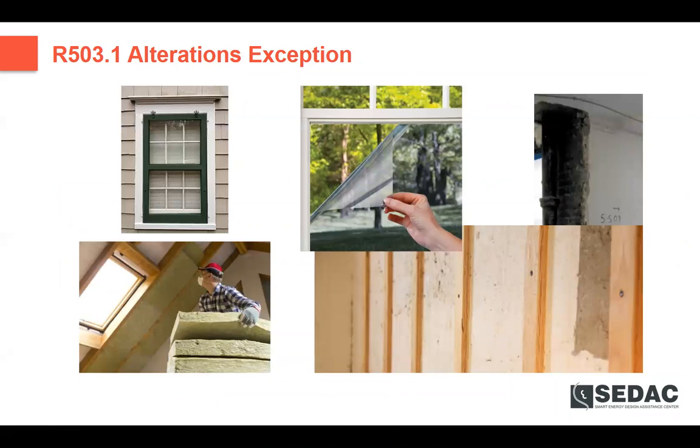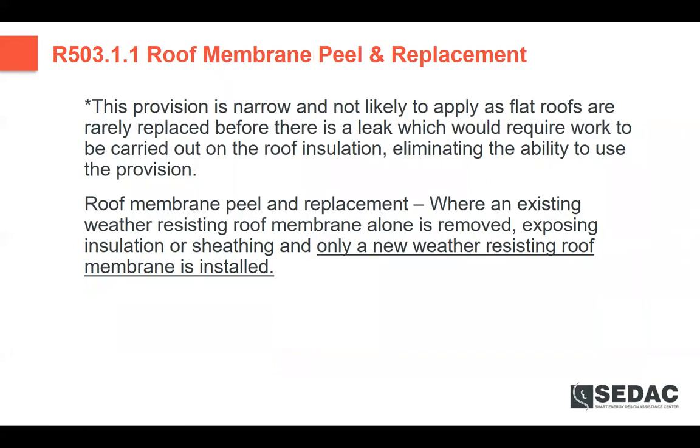In the lower picture there, you can see I've pulled the plaster and lath off and I have just some furring strips. So here I don't have a cavity, so I don't have to worry about insulating the cavity because I don't have one to insulate. The lower left there you can see we've exposed a cavity, and all he's doing is putting a batt insulation to fill the cavity, and that's all they will have to do for compliance with the energy code for the insulation piece.